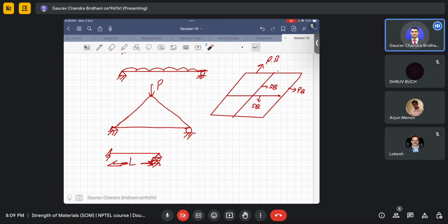Basically, yes. So there is this bearing, where the bridge deck is supposed to attach with the pillars or the columns of the metro. There they have columns, and above, the columns become bulky, wide, and on that wide part the beam or the girder or the box girder sits. At the cap of that column there is some material, because if you put it in direct contact, it will just crack the concrete, so we can't do that.